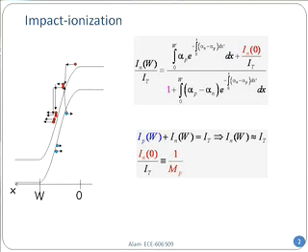If the current has to be constant and this one component has grown exponentially, the other piece must be negligible, right? So therefore, I drop that term which is I_P at W. Of course, I couldn't drop I_P at 0 because I_P at 0 is a huge number. So therefore, you have to be careful how you drop it.